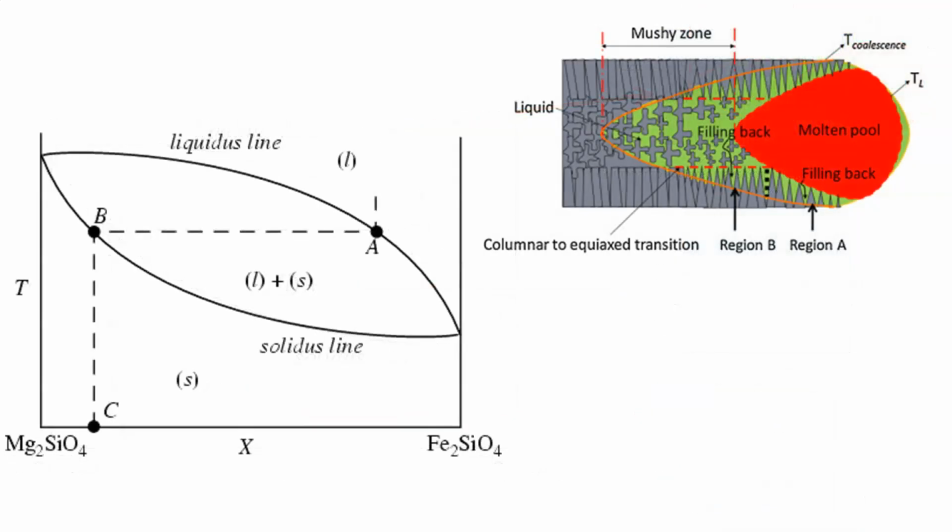If we look at fusion welding, it takes place up in the molten state of metal. From this diagram we have all kinds of information. Your temperature is being brought up past the liquidus line, depending on the alloy, and the temperature reaches a liquid state. So you have this molten pool. As you travel with your heat source, your electrode, going in that direction, the molten pool melts the metal, travels across, and the metal starts to recrystallize behind.